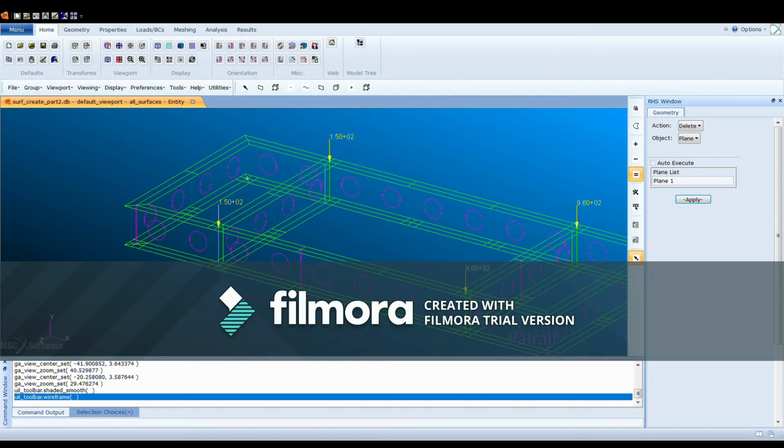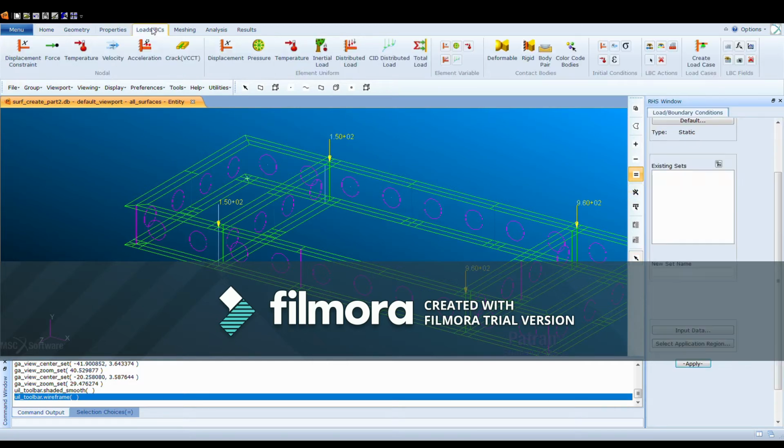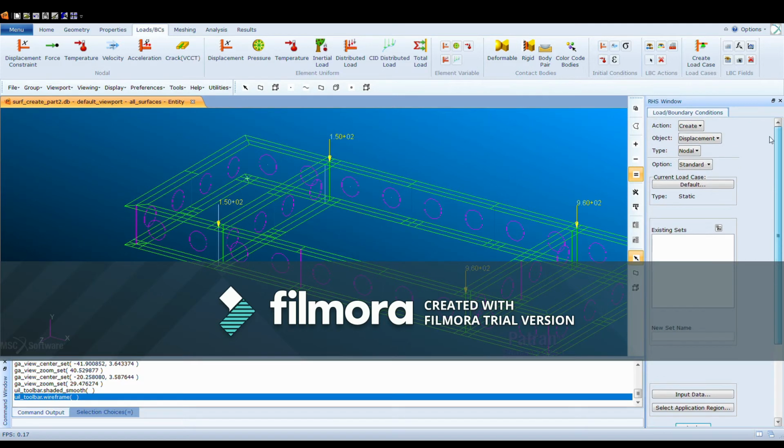So now that we have our working load, we're going to create an operating engine, just our static load for the engine. So we're going to create another load like we had before, and it's going to be a force, and we're going to call it just OP for operating_static_load. And the input data, we're just going to create the force of 0 on X, -100 on Y, and -100 on Z.